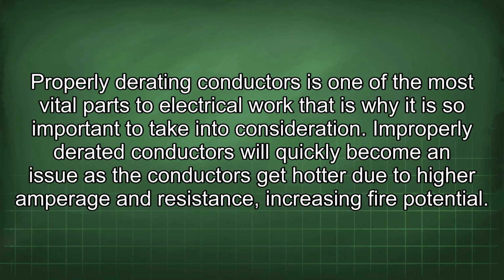safety. Properly derating conductors is one of the most vital parts of electrical work. That is why it is so important to take into consideration. Improperly derated conductors will quickly become an issue as the conductors get hotter due to higher amperage and resistance, increasing fire potential.